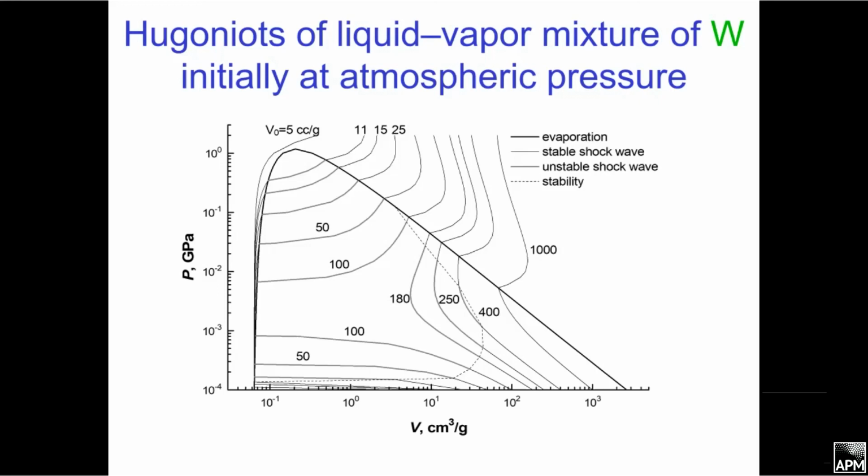At higher densities and lower volumes of the two-phase mixture, we obtain another behavior: first this two-phase mixture is compressed, then the shock adiabat goes along a region of liquid phase, one-phase liquid here.